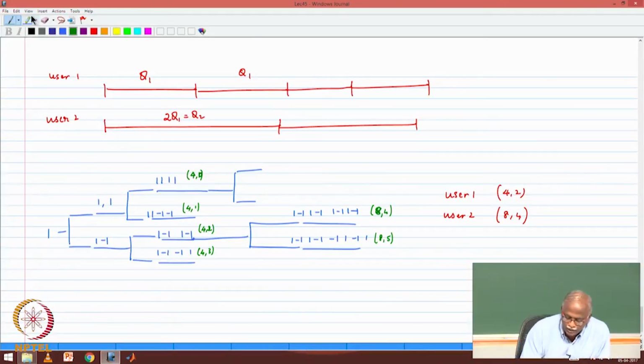Okay, so let me quickly spend a few minutes on the wideband CDMA system, introducing for you one of the key elements of the wideband CDMA system. So, wideband CDMA also uses Walsh-Hadamard codes, but it uses Walsh-Hadamard codes of different lengths, not just a fixed length.